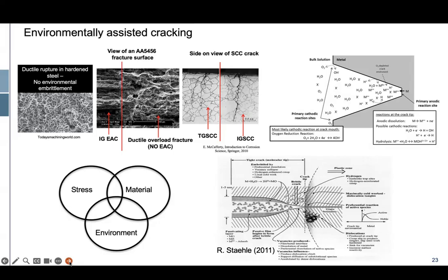And we'll also talk about the effect of cyclic loading in the form of corrosion fatigue, because in real service conditions the loading is never just static. It's usually fluctuating loads. So we need to talk about fatigue and different modes of fracture, like whether the cracks are propagating through the grains or along the grain boundaries, and then it can become transgranular or intergranular based on that.